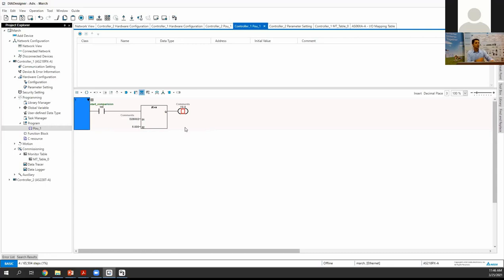What else can we do? We can make, for instance, if it is 5, there is an output, but in the factory nobody focuses on that, so we can give another output when it is higher than 7 volt. So we can make a blinker, for instance, for the light. Okay, so let's say that above the 7, we need to use another comparison. So we can directly copy these two.